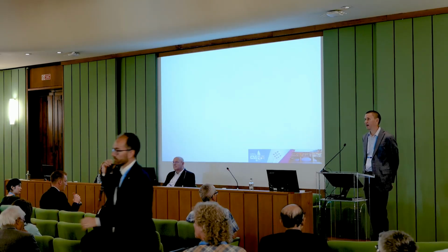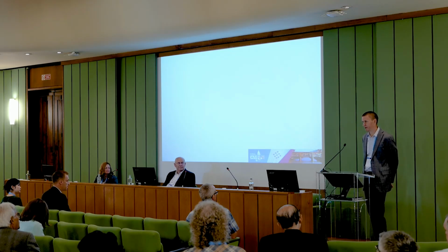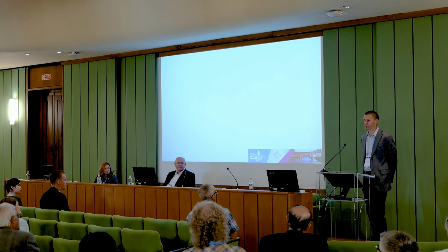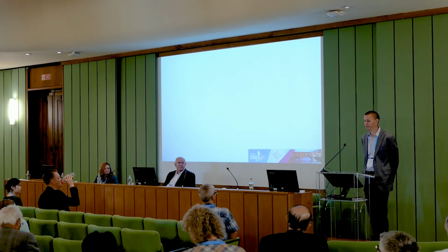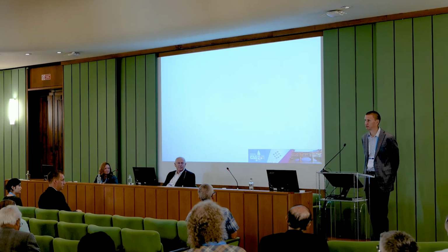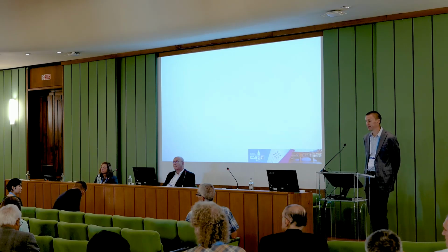Yeah, that's a great question. Simply the scale and range of facilities we're testing in makes that kind of impossible, right? At the smallest end, we have a very stiff 2.7% model that gets tested in a cryo environment. We have less stiff 4% models that are built for 1 atmosphere. We have 10% models. All are architected very, very differently. So the approach that we've taken is just essentially saying, hey, we need to get that aeroelastic data and figure out how to correct for it in the CFD. So there's not a whole lot that we can do to keep that consistent. Perfect. Thank you.